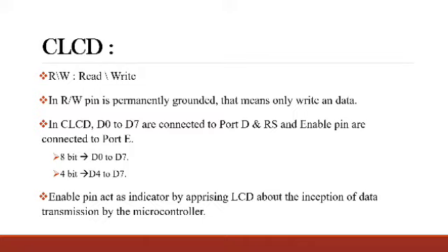The 8-bit means it is connected to D0 to D7. If it is in 4-bit, then we can connect it to D4 to D7. The enable pin acts as an indicator, informing the LCD about the inception of data transmission by a microcontroller. Then we are going to see about the tactile switch.